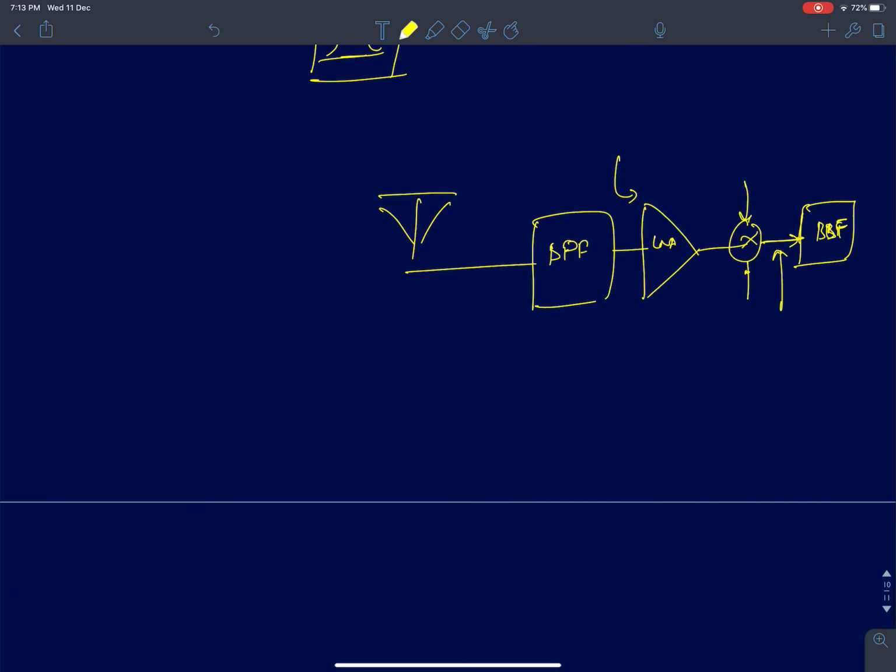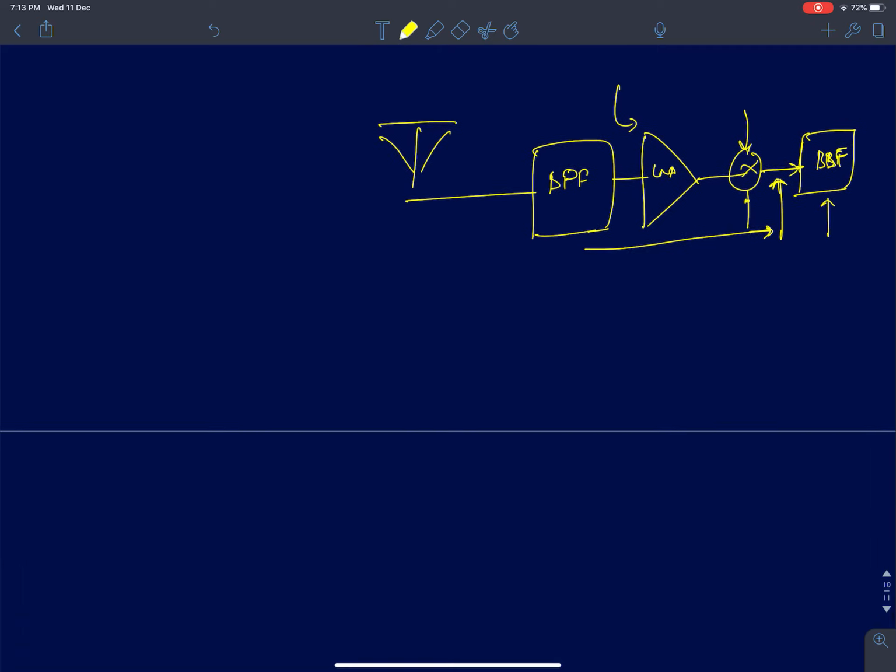Okay, so linearity is a challenge at that point, so you'll have to ensure that. Now the problem is that the bandpass filter now has to be very linear because your signal is coming at low frequencies, and again you will need very strong cutoff, so your bandpass filter has to be very linear. To solve this problem, what they do is they go for the concept of heterodyning.